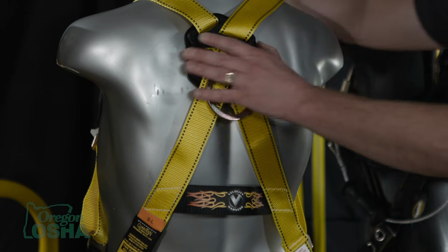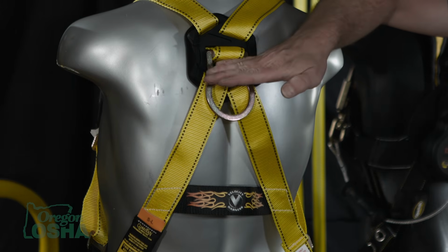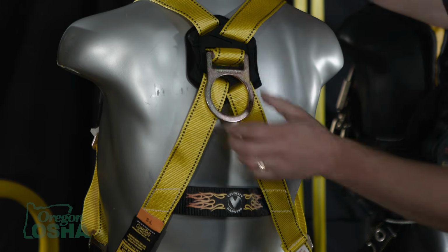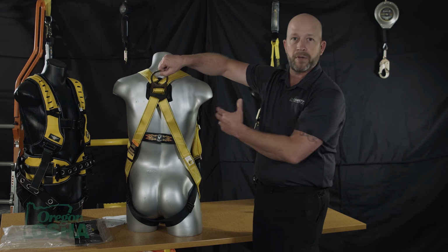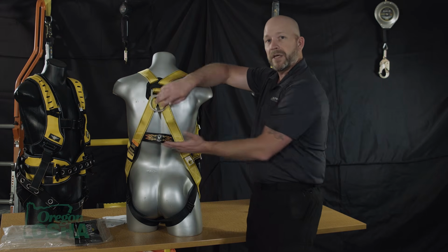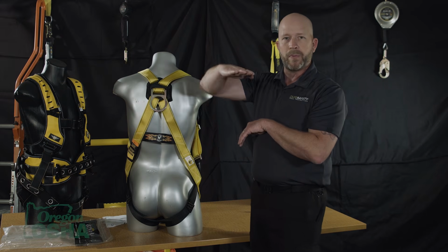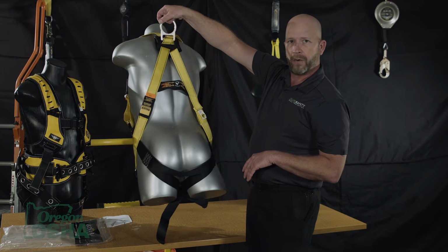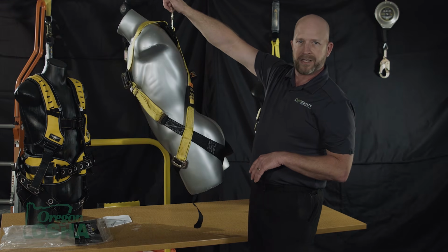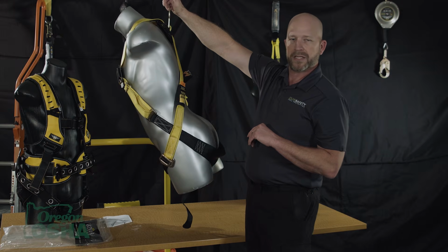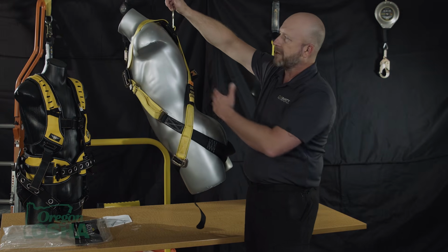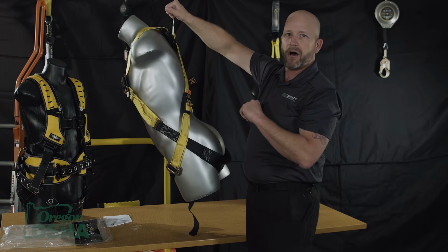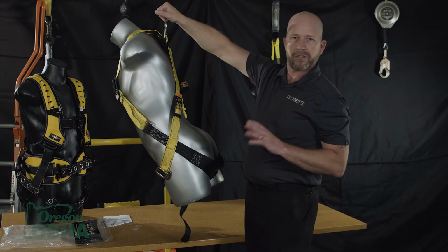And then the last check is, again, make sure that the D-ring is in the upper part of the back, centered in the shoulder blades, so that this is our pick point should we fall. So we don't want it low, because that will make us go into a supine or Superman position. If we fall and we're suspended, we don't want to go much more than that degree. 30 degrees is the maximum that we want to go. With a heavier weight, it'll actually pull the D-ring off a little bit. It's called harness stretch, which is normal.